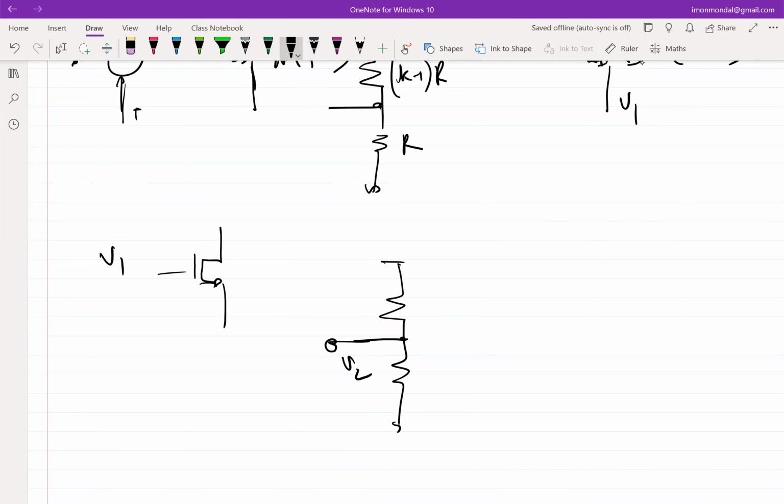Okay. So this source was initially grounded. So there is no way I can apply V2 to source if source is fully hard grounded. Which means I have to remove this ground and connect something there so that the transistor is biased still, right? If I simply connect V2 to that source, we don't know exactly whether the transistor will be biased properly or not. So how do I first set the bias of the transistor?